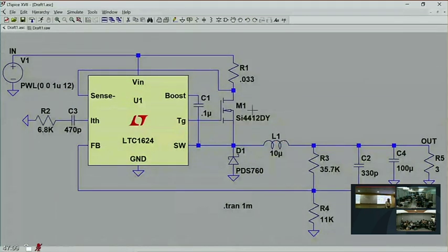Great. So when this thing is on, it's fully turned on, which means that this node is at the input voltage. But to fully turn this thing on, you have to pull the gate well above the source voltage to fully enhance the channel. And if the source is at the input voltage, that means that the gate has to be well above the input voltage. And that's the problem. I've got an unregulated 12 volts, and I'm converting to a regulated 5 volt rail.